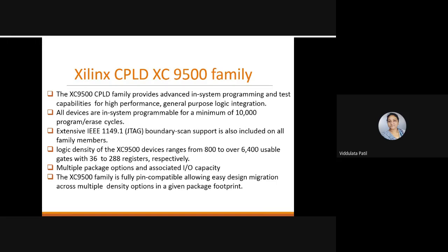Then multiple package options and associated IO capacity are another feature of this Xilinx XC9500 family. This family is fully pin compatible, allowing easy design migration across multiple density options in a given package footprint. So you can easily migrate your design, and easily erase and program this IC.